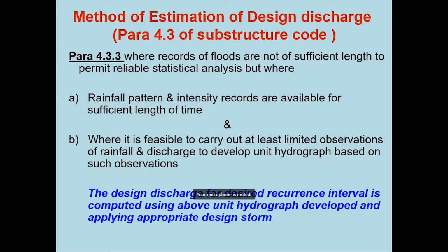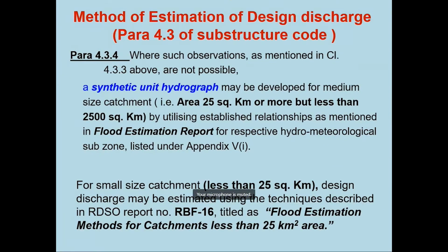This method is called the unit hydrograph method, because this hydrograph is particularly for that catchment area and that bridge location. It is the most reliable, and actual data can be arrived at by this unit hydrograph.